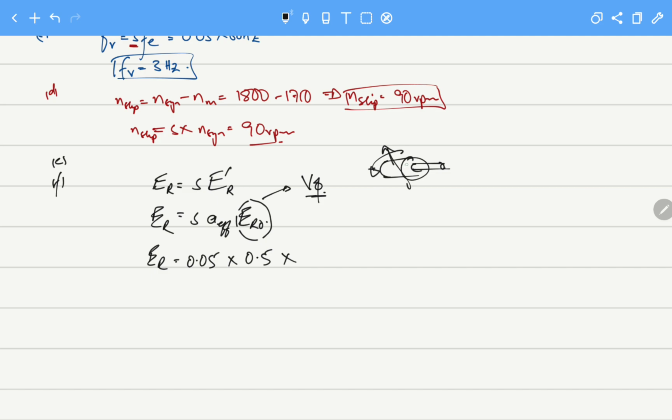That voltage equals the voltage being supplied. For the per phase equivalent circuit, it is a Y connected motor with the line to line voltage given, so we convert this into phase voltage. The induced voltage on the rotor becomes 6.64 volts per phase.